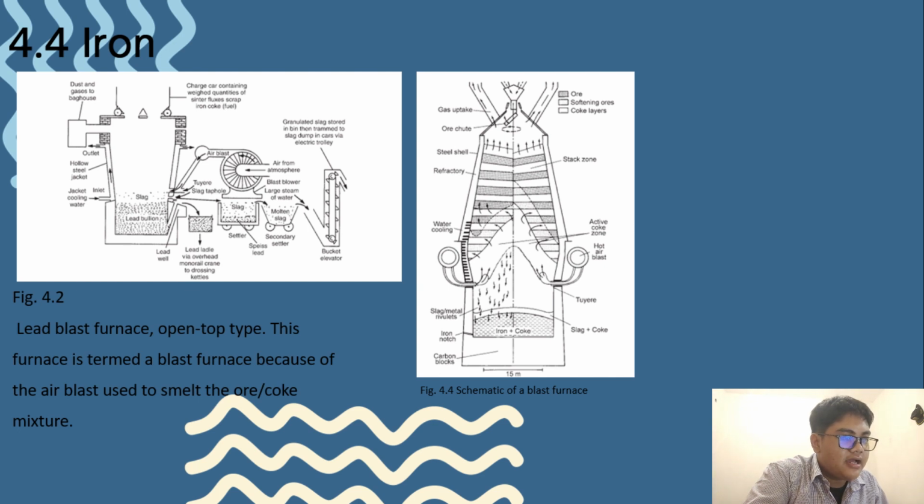Steel, which is iron containing between approximately 0.1 and 2% carbon, combines the toughness of wrought iron with the strength of pig iron. Steels can be made from wrought iron by heating the iron for a long period of time in a red-hot charcoal fire. The hot iron absorbs carbon from the charcoal so that carbon atoms diffuse into the iron layers. The result is an iron-carbon solid solution alloy that we know as steel. The increase in carbon also provides other advantages in the strengthening of steel when it is quenched from elevated temperatures.